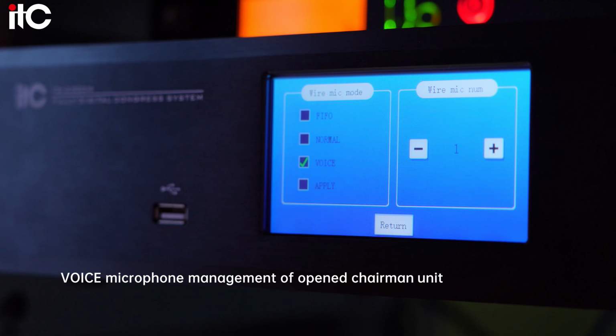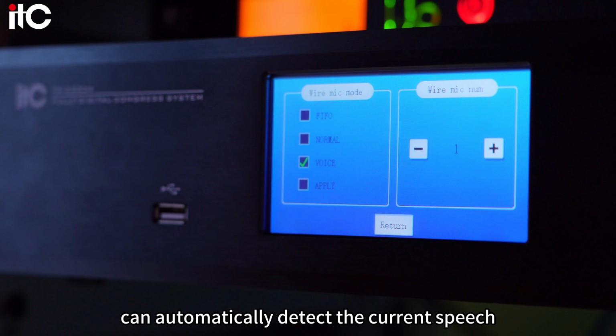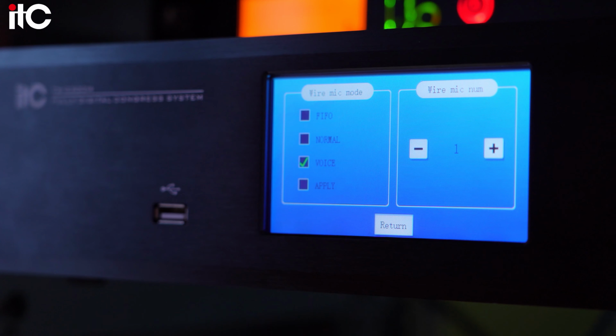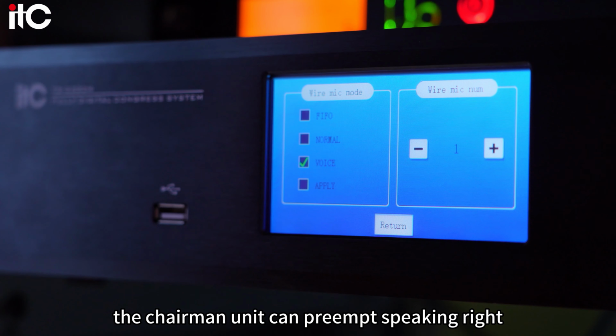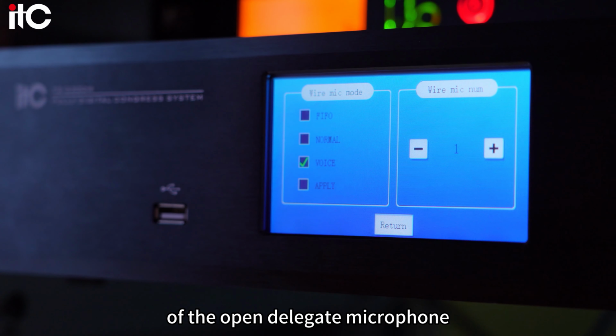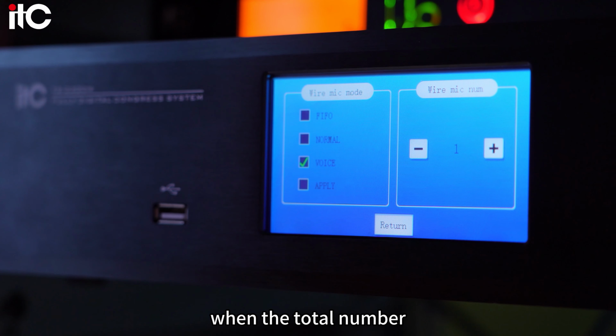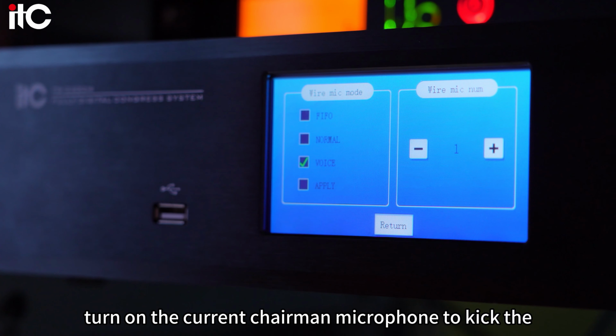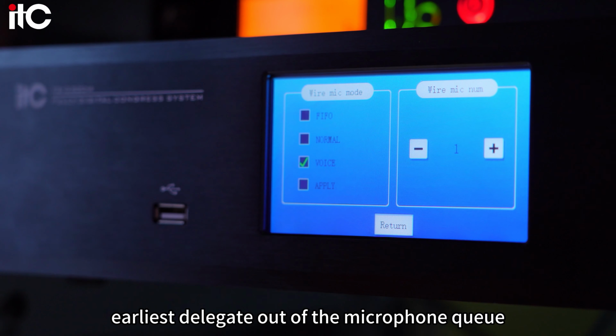And for the chairman unit, voice control mechanism, the chairman microphone can automatically detect the current speech, and the microphone can be automatically turned on by speaking to it. Preemption mechanism. The chairman unit can preempt speaking right of the open delegate microphone. When the total number of opened microphones reaches n, and there are some delegate units, turning on the current chairman microphone will kick the earliest delegate out of the microphone queue.